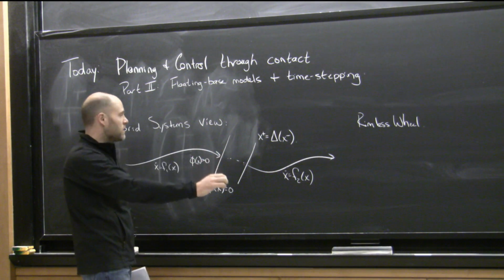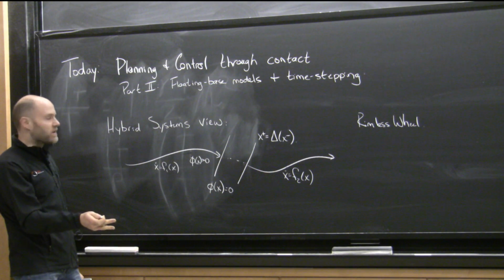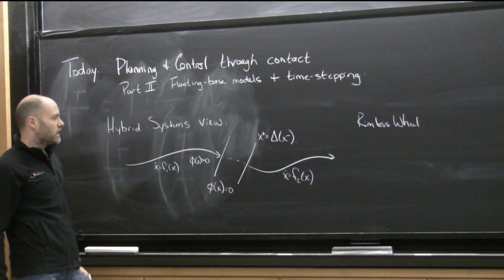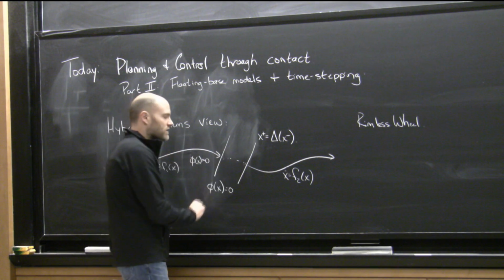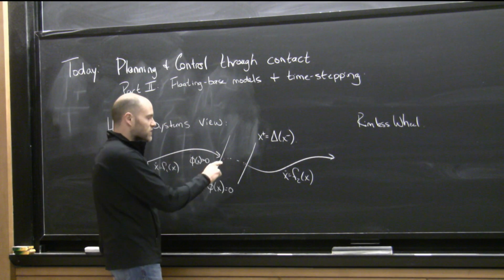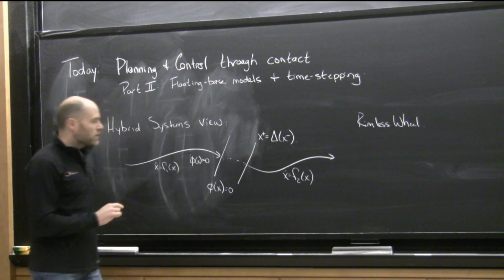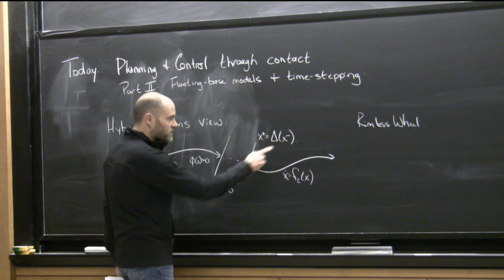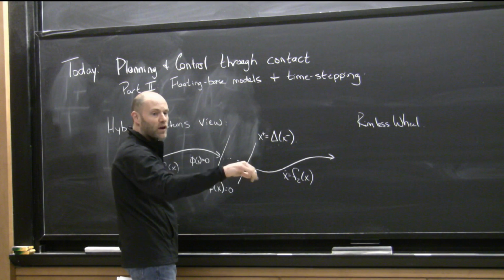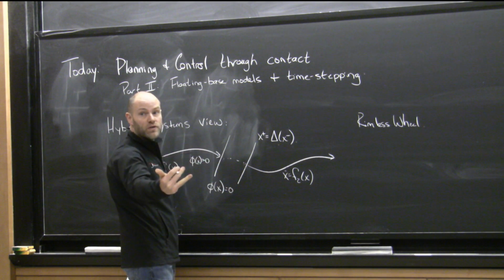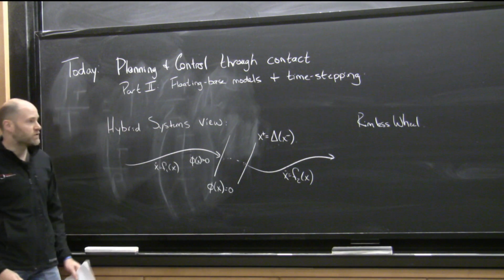Explicitly, we modeled the event of the foot hitting the ground as a discontinuous event, which was a guard in our phase portrait, and then there was an explicit jump, which looked like cosine of 2 alpha. You lost velocity proportional to cosine 2 alpha in the jump. The other thing that the jump did was it actually reset our coordinate system so that whatever foot just hit the ground became the pin joint for the pendulum, and you started again. Right, so we made heavy use of this sort of modeling approach in the rimless wheel.